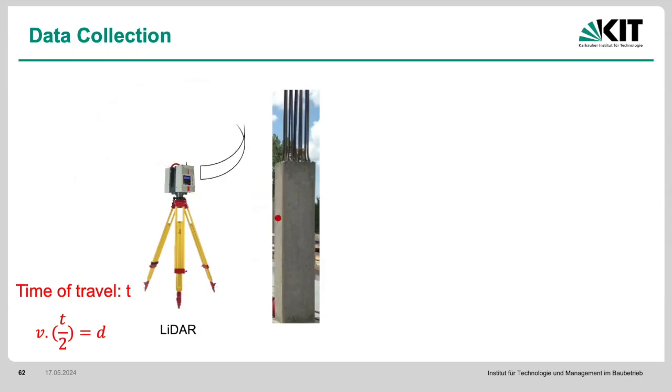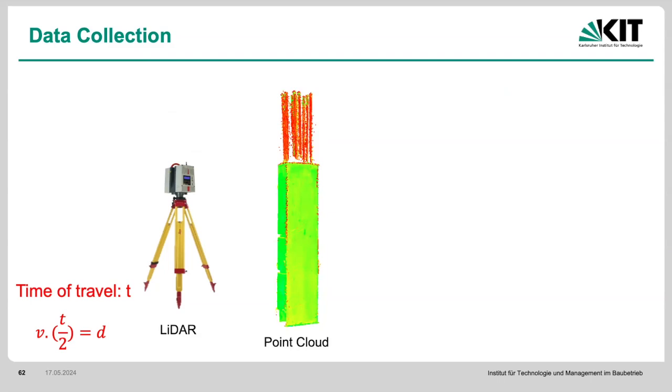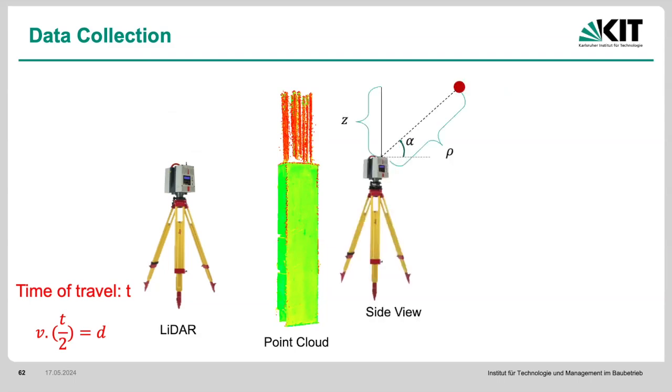And then the signal incrementally changes vertically and then horizontally, so you get a full panoramic vision. However, it's not gridded. Why? Because it's gridded in the spherical coordinate system. So what it gives us is a bunch of points whose distance is identified through the speed of light in this medium. So here, the distance is actually a direct distance.